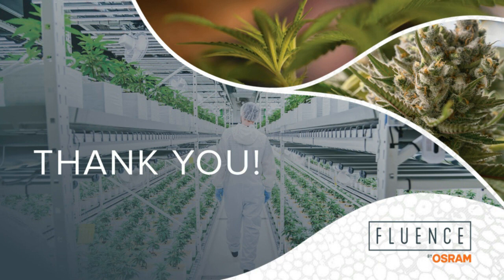Good deal. And so what I like to tell guys is that VPD is an indicator. It's not a direct measurement of transpiration in the plant, right? And so I like to manage the environmentals and say, look, what does my temperature need to be? What does my humidity need to be for me to be successful? And then use those two data points to correspond a VPD, right? And then once I get that corresponding VPD, then I can say, all right, look, for my future grows or for any cultivator that's coming in here after me, this is the VPD range that you should be targeting based on the environmental set points of temperature and humidity.